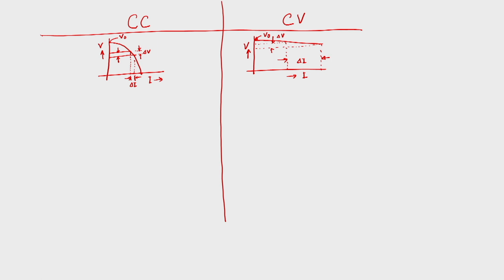So, what is the difference between these two characteristic power sources? Here the rate of melting is almost constant, but in the other case the rate of melting can vary while arc length remains constant.